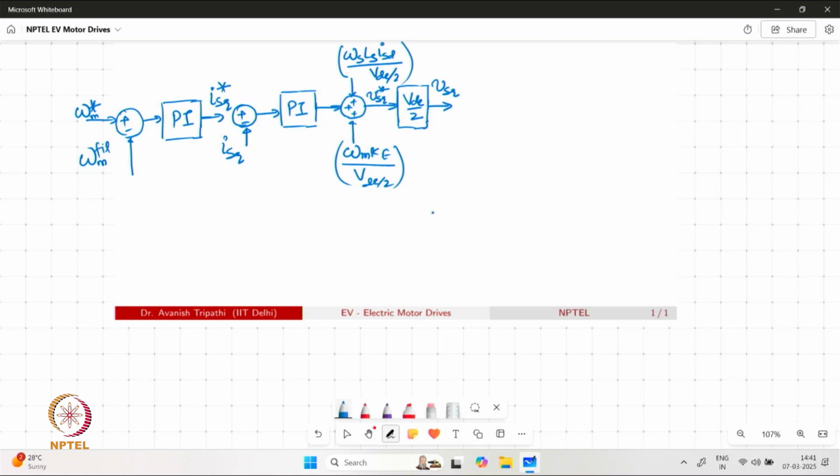The output generated by inverter in the DQ frame of reference, VSQ, is basically fed to the machine, where the model has two nonlinear components which are getting subtracted from the voltage and there is an RL block corresponding to the resistance and inductance of the stator winding, and we are finally receiving the ISQ current.